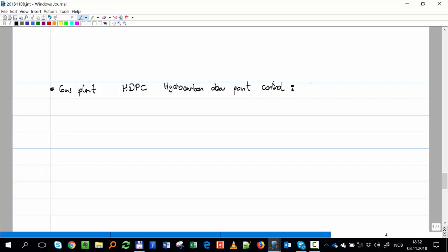One of them is called JT expansion, basically Joule-Thomson expansion. What does that process use? Exactly what we discussed with the choke. You remember, I have an isenthalpic expansion. What happened with the fluid when I reduce the pressure in a choke?